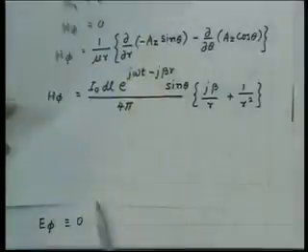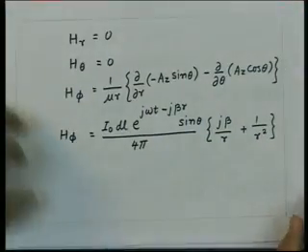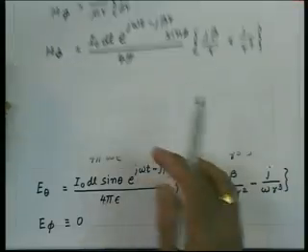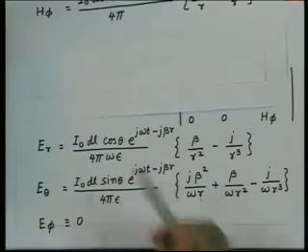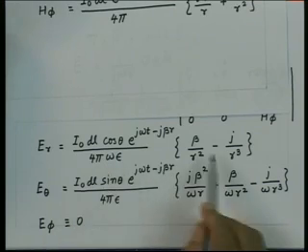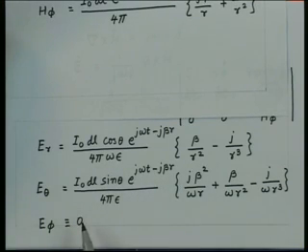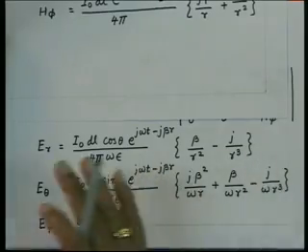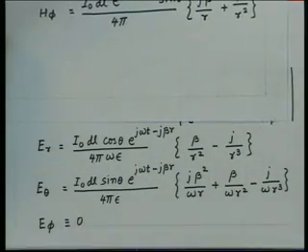Now, we try to look at the various terms which we have got in the electric and magnetic fields. So, if I look in general at the field expressions, the H phi and these two components E r and E theta, I notice there are three types of field which are generated by the Hertz dipole, depending upon the variation of the field as a function of distance.